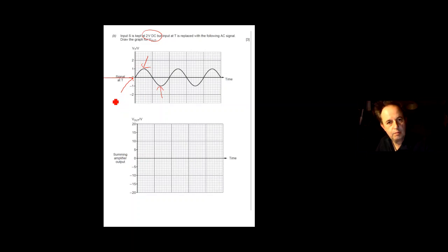So what I have for V out there would be minus 40k, brackets, and a constant 2 volts over 20k. What was coming in was 0 volts at this point, so I'll put in 0 over the 10k. If you work that out, the voltage at that point would be minus 4.